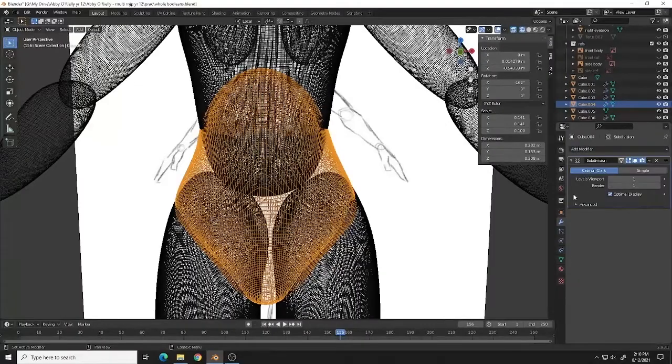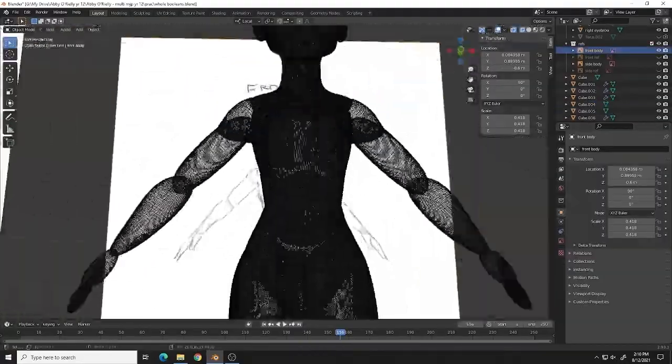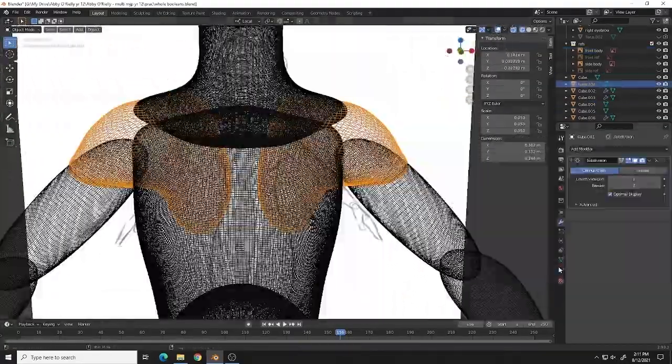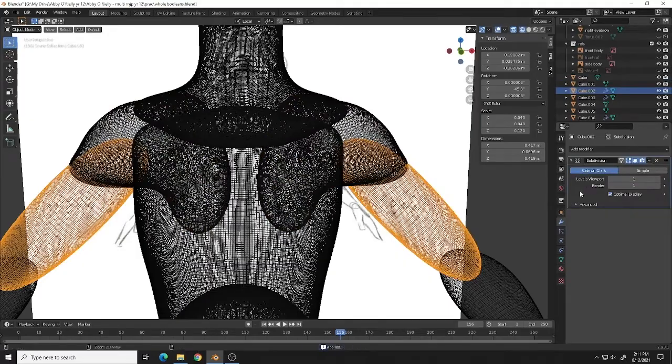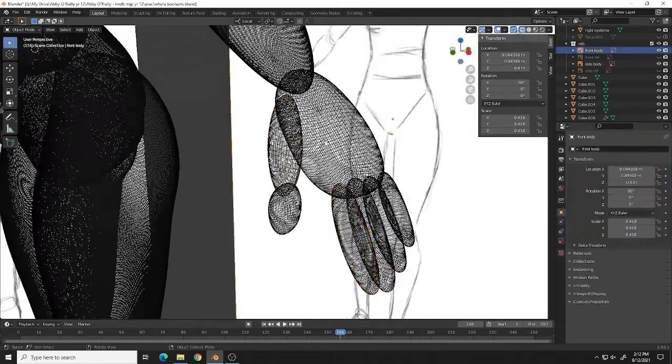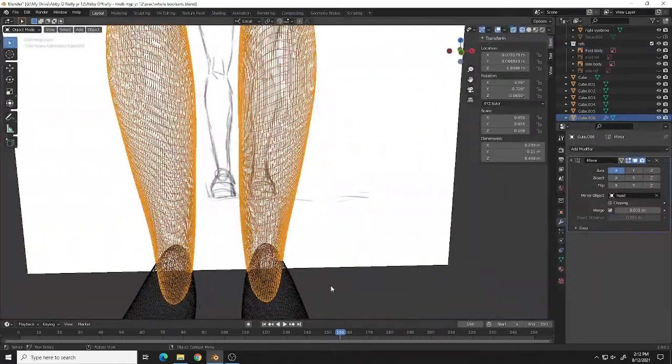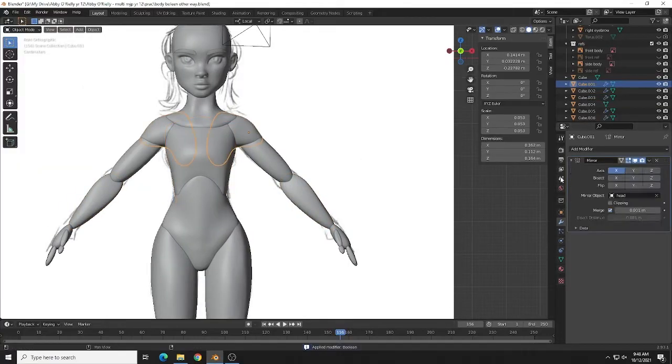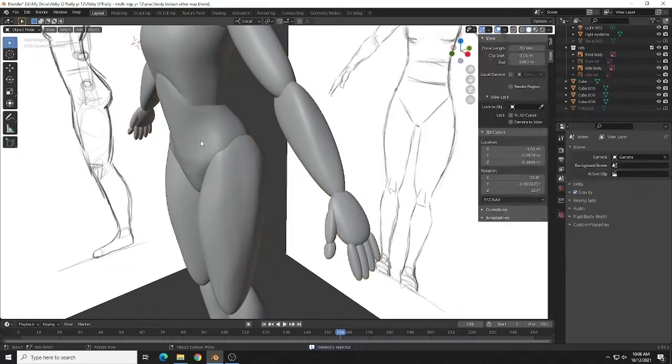Once I was happy with the sculpted model, I moved on to utilizing the Boolean modifier to connect all segments of the body without impairing the mesh. Before this, it was essential to apply all subdivision and mirror modifiers to ensure all mesh exists permanently within the scene. The modifier must be added to the mesh above and then applied as a union to the mesh below to avoid unwanted mesh removal.